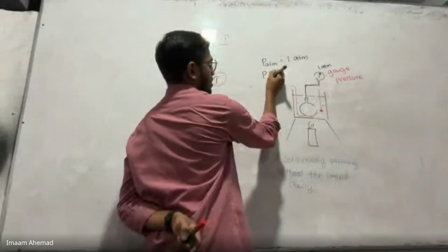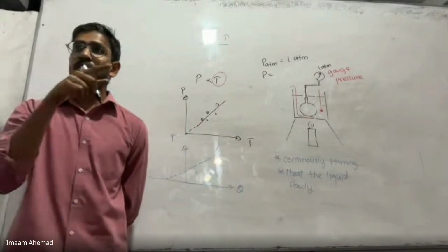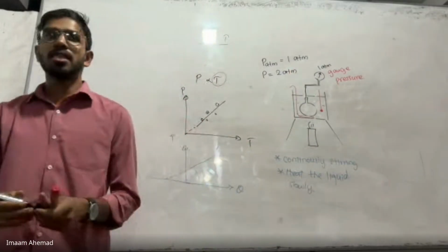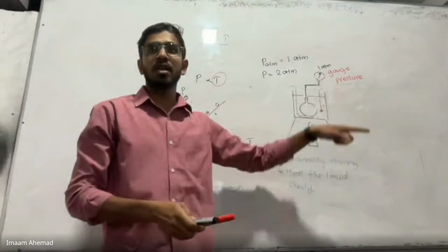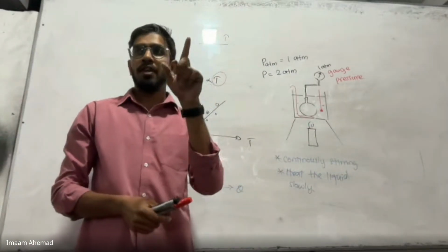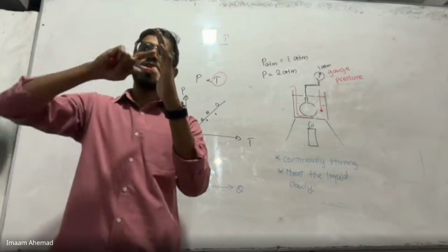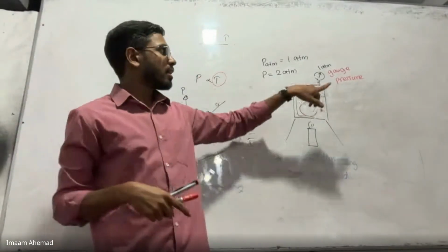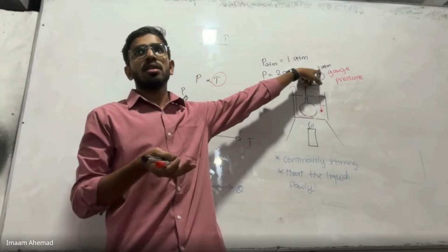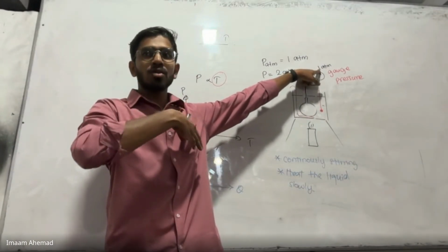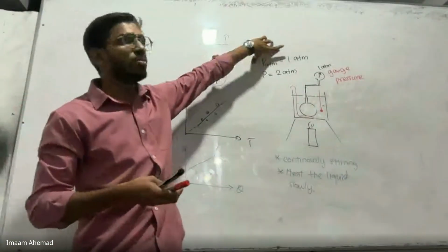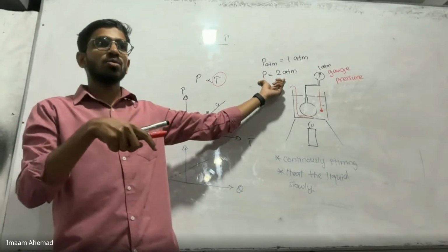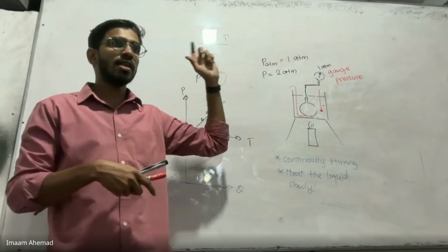Then what is the pressure? Now the pressure is 280 m. Is it clear? This one is reading gauge pressure. So if it is reading 180 m, it is 180 m above the atmospheric pressure. If this one is reading 280 m, then what's the pressure? Okay, so you will have to add the atmospheric pressure to get the actual pressure. Then only you will get the actual pressure.